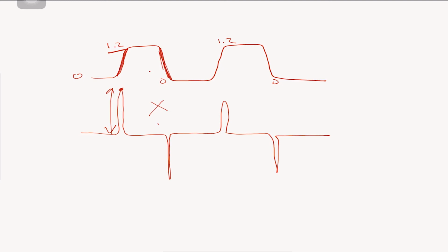And I explained earlier, when the current is more, that means the transistor is faster, right? It carries more current, information quickly, strongly, which is good for frequency. You can run it at a much higher frequency, but when you run it at high frequency, you also consume a lot more power. The leakage power is a bit different. Maybe I'll touch on it in another video.